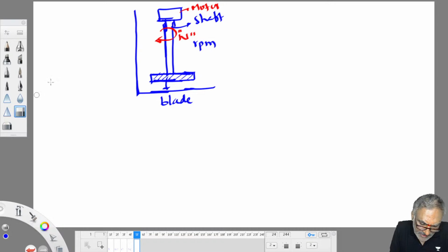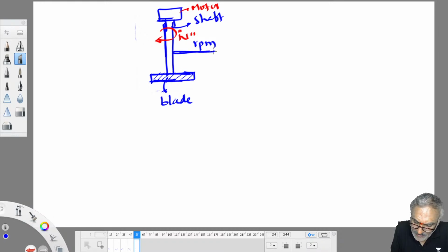Once it rotates inside the tank, what happens? It induces a velocity gradient. Velocity gradient means the water molecules move inside with different speeds. If you draw the velocity profile, velocity is maximum at the periphery, and as you go towards the shaft, velocity keeps on decreasing like this.